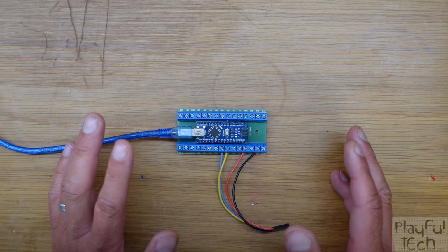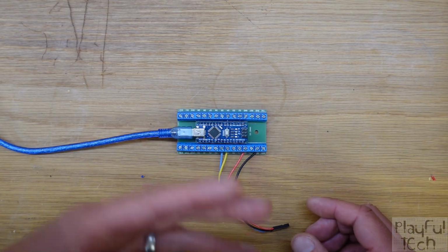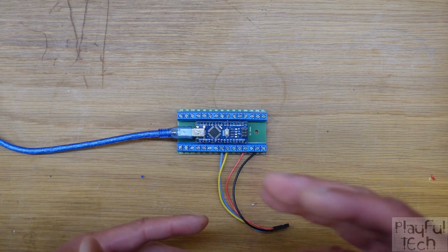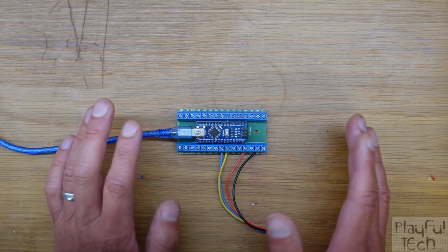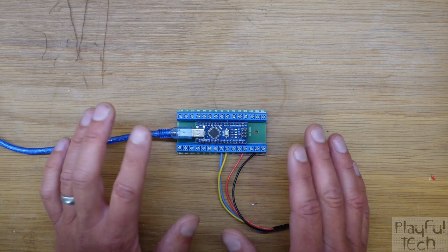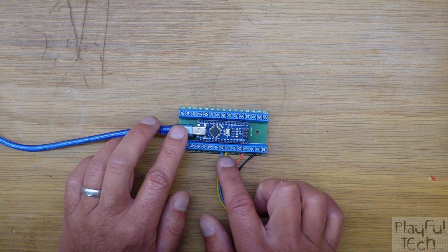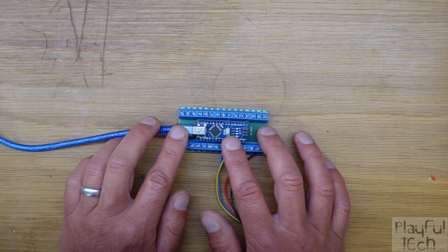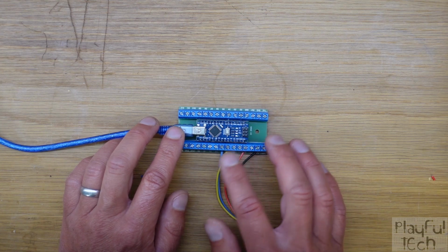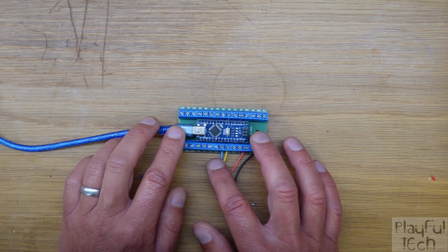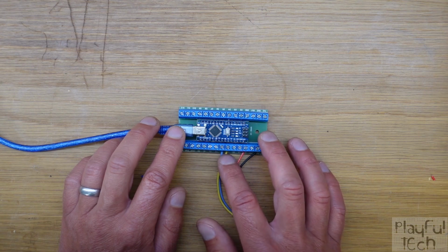Just as I described that there are only some pins capable of analog input and some capable of analog output, there are also some GPIO pins with other special features. And these 2 GPIO pins are the ones that are used by the Arduino's I2C interface. A4 is the data line and A5 is the clock line.